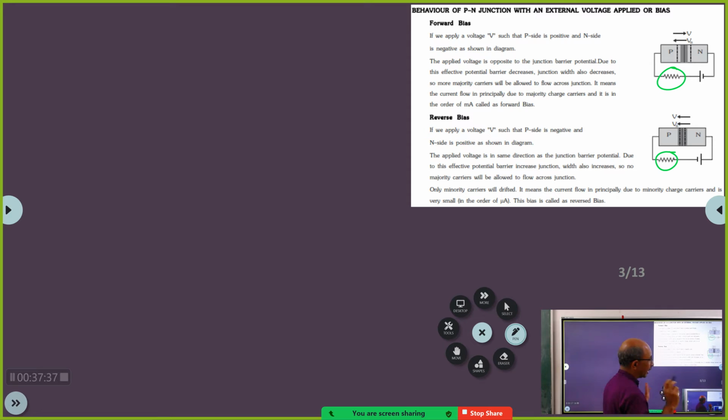Now, you see here, there are some important things. In both these circuits, in the forward bias, I will make this variable. I will vary this from 0 to say some voltage V1. So as I increase the voltage from 0 to 0.7 volts, the depletion layer is still there, and at 0.7 volts for silicon, the depletion layer will vanish, the potential energy barrier will collapse.